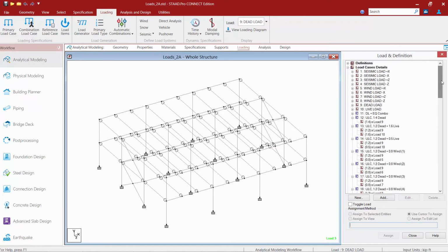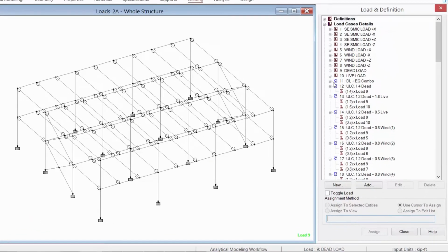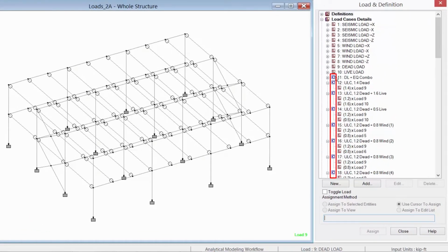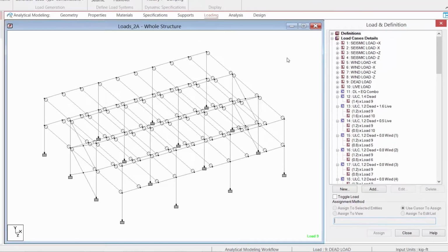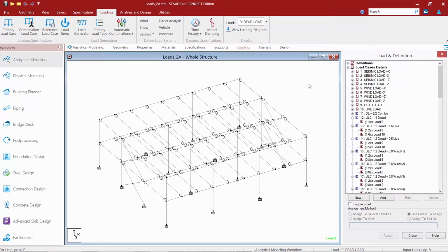created. Now these are traditional load combinations. Again, those are an algebraic combination of their results. We know that they're load combinations because we're going to see a blue C with a square over next to them. Now, these types of load combinations should only be used in a linear elastic analysis. They're not appropriate for any type of second order analysis, including models where P delta might be required, or any models that have tension only or compression only members.